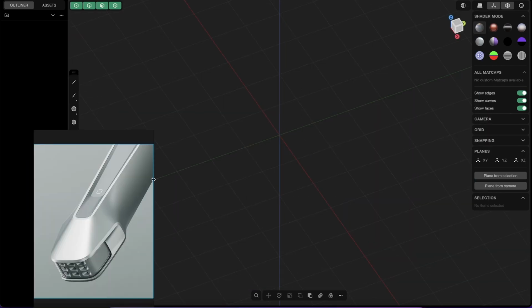So delete the cube. And first of all, we want to create some curves here. Everywhere where we have hard edges, we just want to create curves. So we want to build the spline cage. It's always the same. Doesn't matter if you create a car, a helmet, whatever. You always have to start with the spline cage. And once you have that, then you can start to break everything down and fill in the surfaces and make some surface transitions. It's always the same.